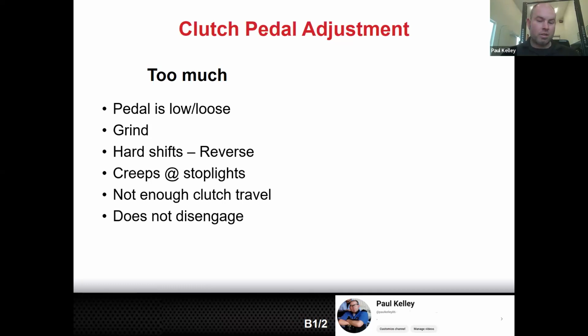He puts a clutch slave cylinder in it. He puts a clutch master cylinder in it. And basically the whole diagnosis was it's not releasing all the way. So therefore, the clutch slave and clutch master must not be throwing the fork all the way. So he does all this clutch stuff, and then he's like, well, it must not be bleeding. So he bleeds it, and he bleeds it. He spent like a whole day bleeding this car. And then he's looking at the fork, and if you throw the fork, it didn't seem like it was going the whole way. So he added little nuts and shims and stuff and tried to shim it up.